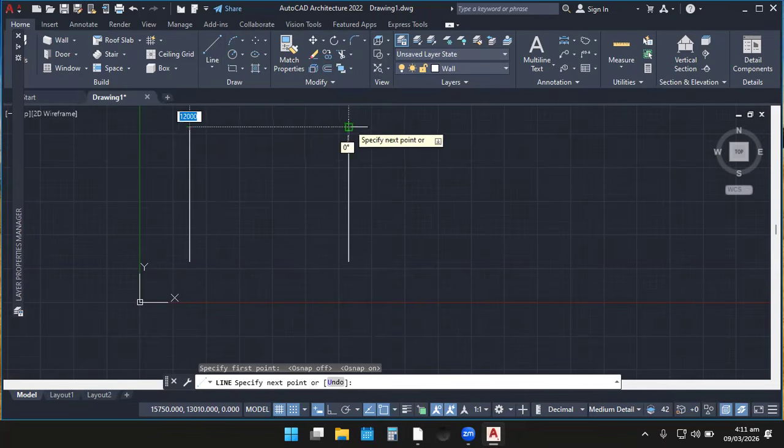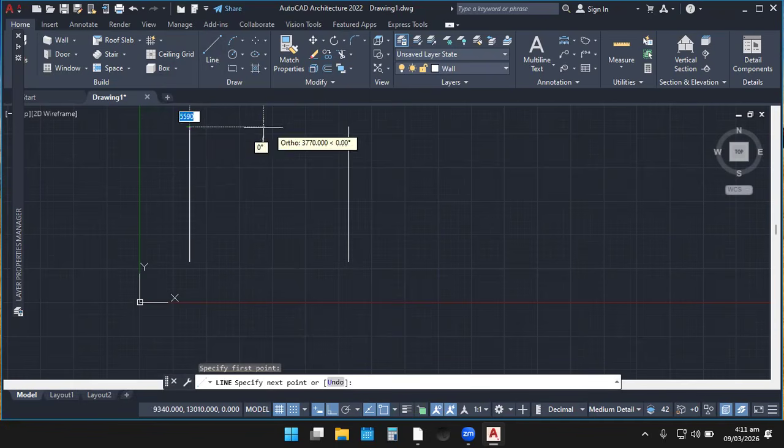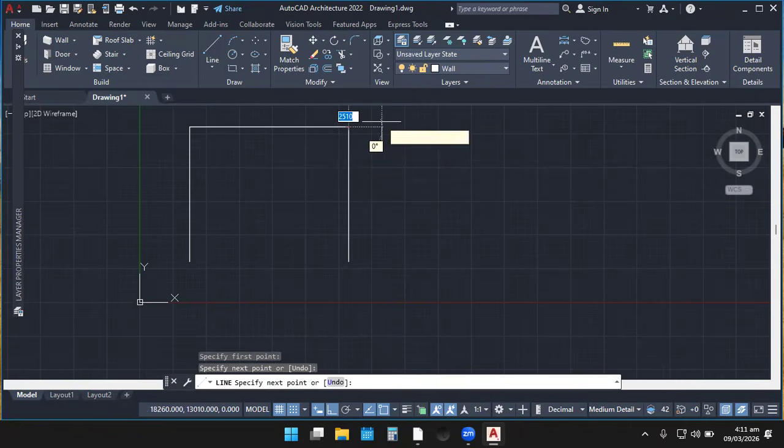You can drag from end to end. But you see that the auto is not on, so the line is also misbehaving. So I can just escape whatever I'm doing, click escape on the keyboard, and come and activate the auto. You see, now I pick the line again. Now I take the corner of that line and bring it to the other corner, I click, I release. Then after doing that, click escape to release the mouse.